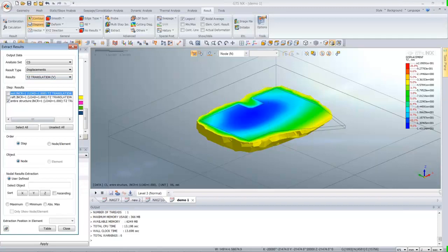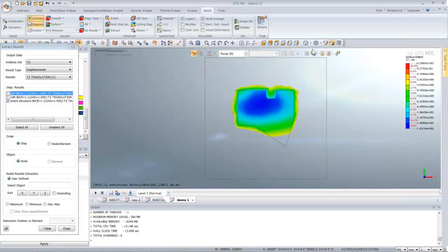You can select the nodes for which you would like to check the results, or you can put them in order of the steps. So we'll see the nodes, and here we can select the objects. So we can go to the top view from here, and we can go to the front selection only view option, and we can make a box around the nodes for which we want to get the results, and then accordingly we will take, I'll use this polygon selection.